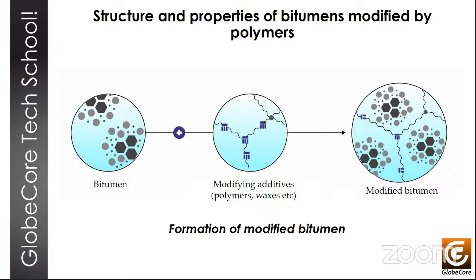At a higher concentration of polymer in bitumen, the compositions can be considered fibrous or layered. The matrix turns into a medium that transfers the loads to the fibers, and in the event of fiber breaking, it redistributes the stresses. Such compositions are characterized by increased strength, elasticity, and resistance to fatigue fracture, which is especially necessary to ensure the operational reliability of the material. The process of destruction of such composite materials begins with the growth of microcracks, and then upon encountering a particle of high modulus rubber or polymer, it slows down, then decreases and even stops altogether due to relaxation of overtension at the tip of the crack.